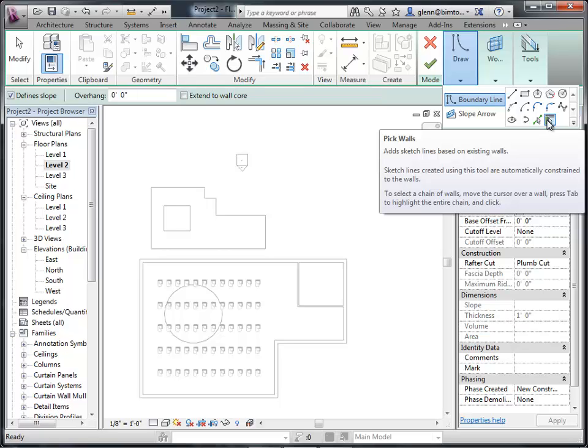So here's a roof like that. We've started getting to be very careful about how we can use overhangs, especially in the age of thinking about sustainability and passive design. If we want sun able to enter the building in the wintertime, when the sun's very low in the sky, but sun blocked out of the building in the summertime, when the sun's high in the sky, you can actually use the overhangs to do that. It's a really cool way of providing shading so that we're not getting a lot of heat load from the sun on our windows during the summertime.